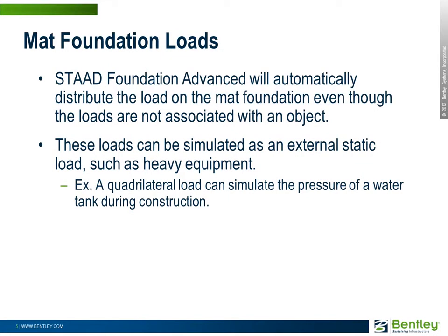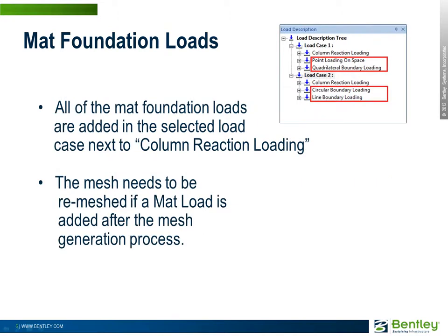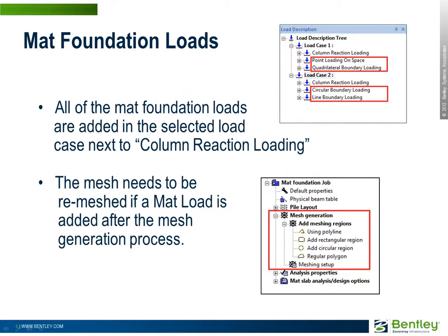To continue discussing the mat-specific foundation loads, STAAD Foundation Advanced will automatically distribute the load on the mat foundation even though the loads are not associated with an object. These loads can be simulated as an external static load, such as heavy equipment. For example, a quadrilateral load can simulate the pressure of a water tank during construction. All of the mat foundation loads are added in the selected load case next to column reaction loading. Also, the mesh needs to be remeshed if a mat load is added after the mesh generation process.